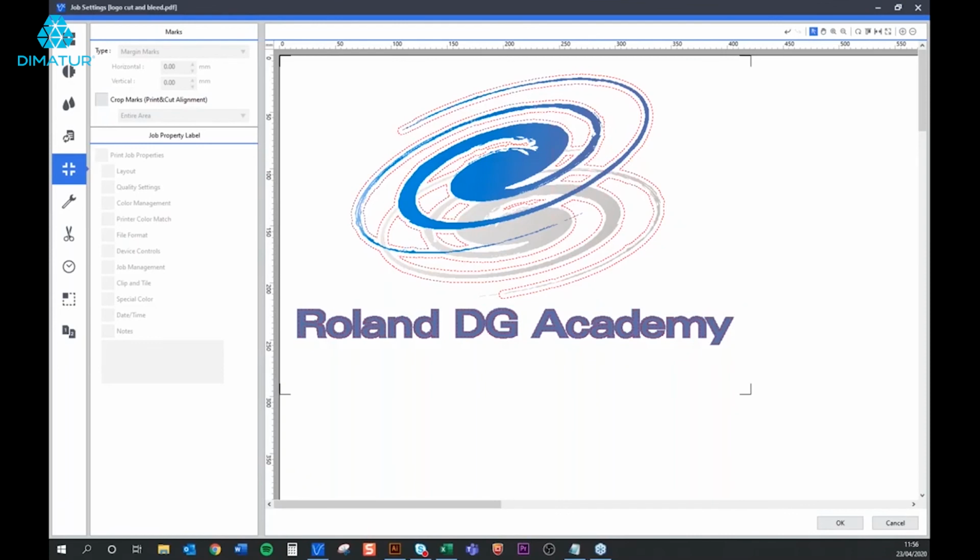It just has a default weight, as you've noticed. So what I might do as a workaround in the meantime from that comment is to put an offset of 1 millimeter. So where you have your margin marks, if I then go to the horizontal and vertical offset, if I put a horizontal and vertical offset of 1 millimeter, it will move those margin marks 1 millimeter outside, and then just make sure that you cut inside the margin marks, which means by 1 millimeter you would lose the margin marks. So I hope that makes sense.